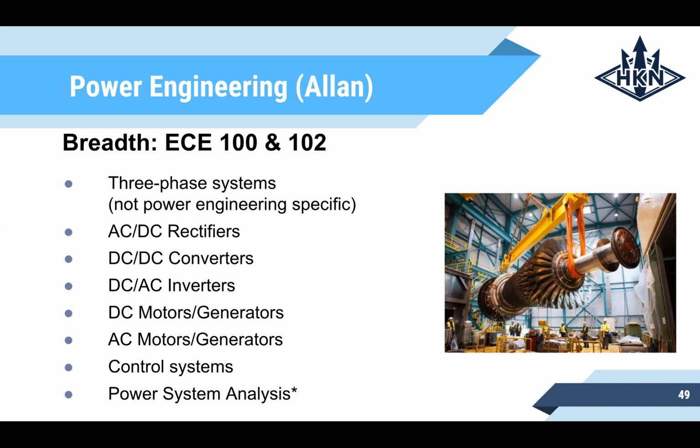You deal a lot with rectification and converting DC to AC, DC to DC. If you want to step down a DC voltage into another DC voltage, you can use a buck. If you want to step it up, you can use a boost. If you want to do both, you can do a buck boost. You delve a lot into those converters. Obviously, if you want to change DC to AC, you use an inverter to easily switch back and forth from a constant waveform into a sinusoidal waveform, and we delve a lot into that in our classes.